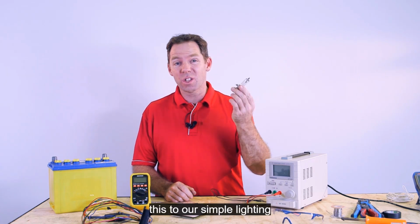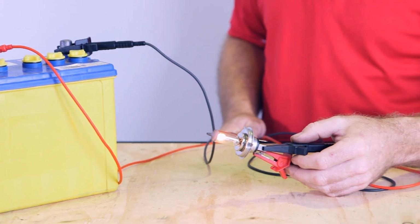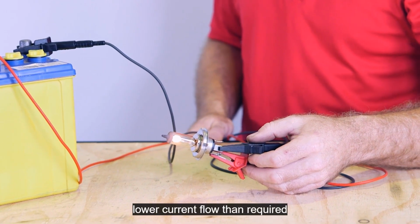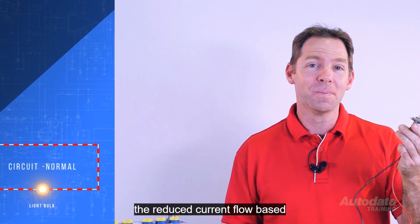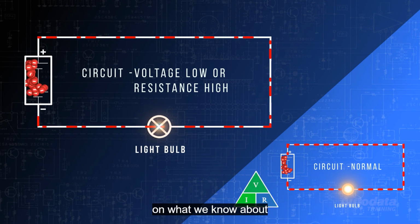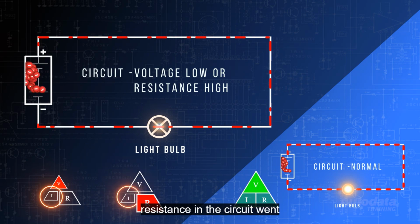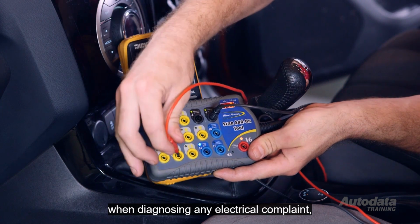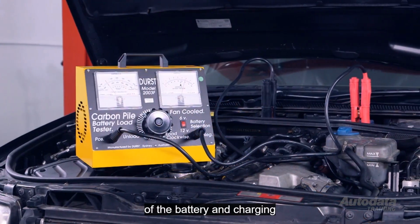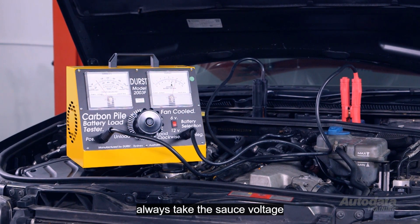Let's apply this to our simple lighting circuit. The problem we see is a dim globe. This must be caused by lower current flow than required. So, what could have happened to cause the reduced current flow? Based on what we know about Ohm's law, either the voltage to the circuit went down or the resistance in the circuit went up. This is why, when diagnosing any electrical complaint, we must verify the health of the battery and charging system as a first step. Always take the source voltage element away from the concern.